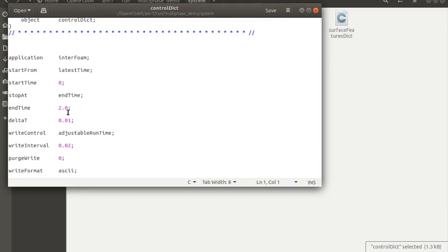So in order to check the simulation is working perfectly, that the inputs are within the control, initially you have to give a smaller amount of time, I would say 0.1 second. So within that time we can check whether the simulation is performing in the expected way.